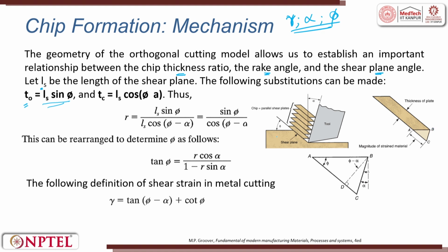You have to use all the graphs. This is the rake angle, and this is the shear plane angle, phi, and the shearing operation happens. Because of the severe plastic deformation, the chip is getting formed. Now I try to draw a small triangle in this. This is the thickness of the plane, or a plate.